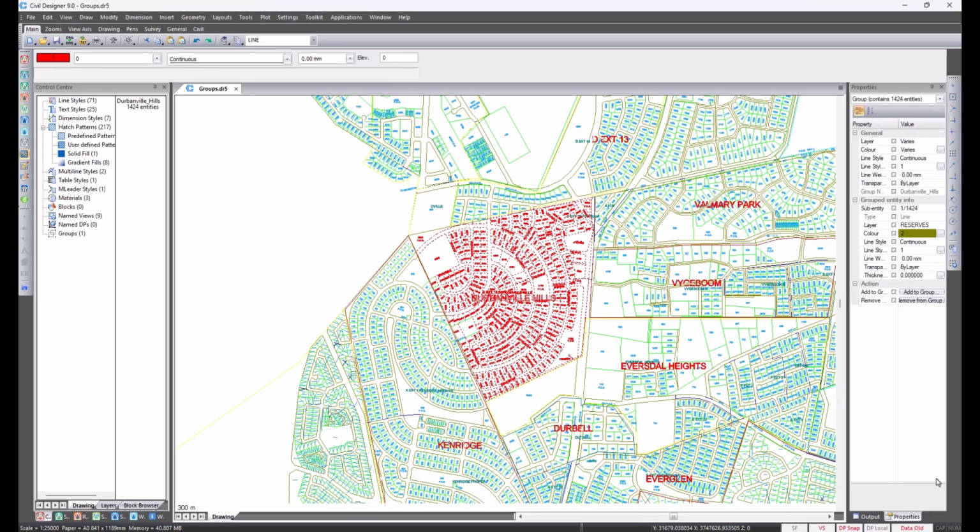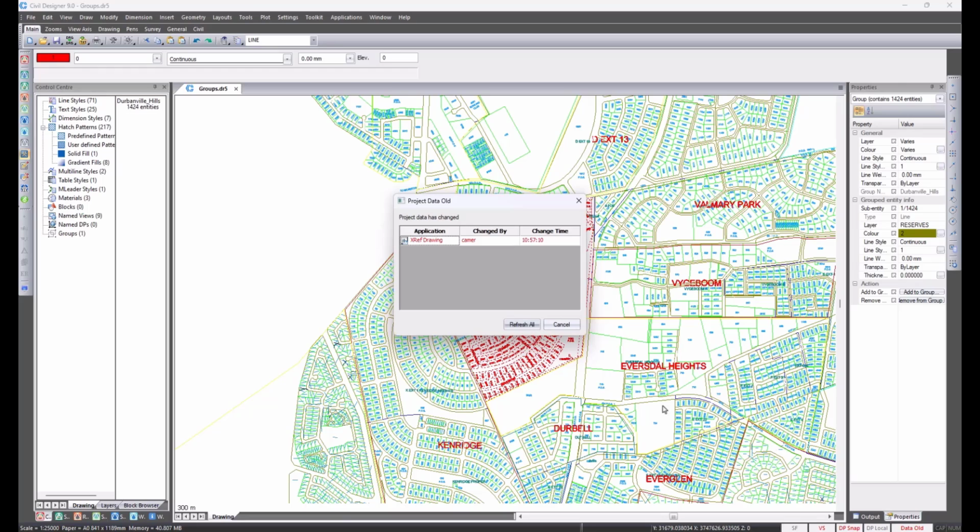This tab, still written in red, says data old. If I go and click on it, I can go and refresh the Xref. And I'll go into a lot more detail as far as this is concerned a bit later. But if I place my cursor here, this indicates the position or the location of the Xref. I'll then cancel it here.